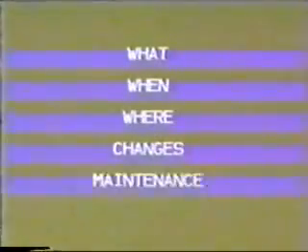Did you figure out some questions? If your questions fit in the following categories, then they'll probably be helpful. What were the symptoms that caused the operator to report a problem? When did the operator first notice the problem developing? Where did the problem occur? Has the operator made any changes in an attempt to correct the problem? When was the last time maintenance was performed on the packing? Further checks in maintenance logs may provide additional information.